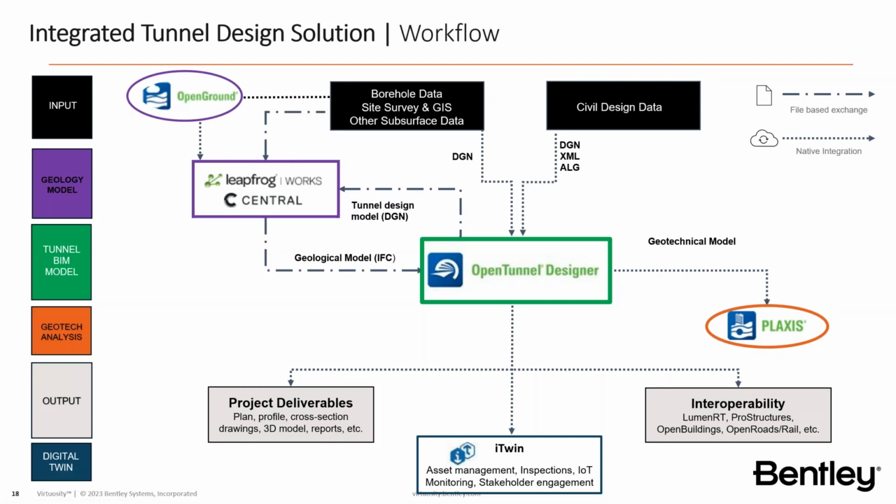This means that in Leapfrog, you'll create the 3D model, the 3D meshes with different properties for those soils. And from there, you have the option to export the soil meshes through IFC, and OpenTunnel will be able to create those meshes inside OpenTunnel. We will be able to add material properties with analytical properties also that are targeting Plaxis. And then when you create your physical model, the tunnel, we will cut those soil meshes.